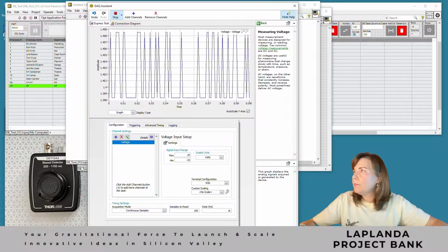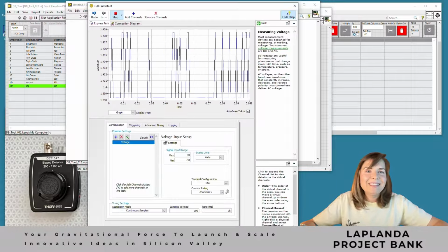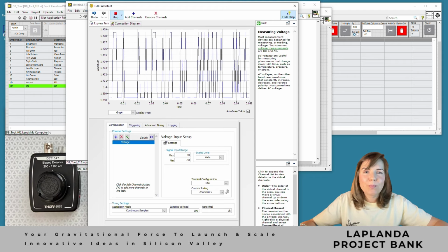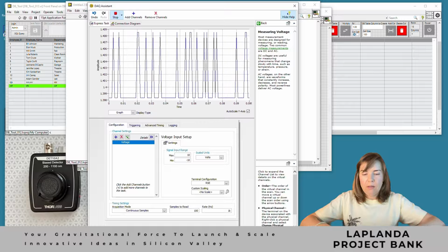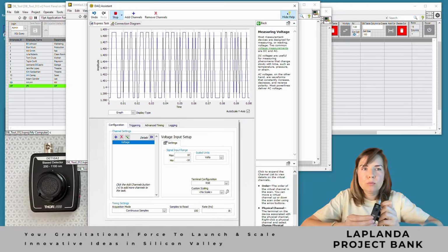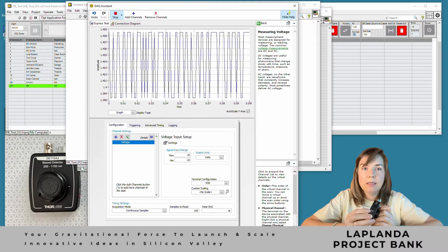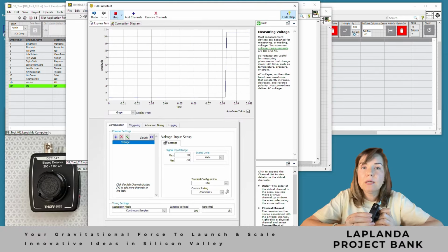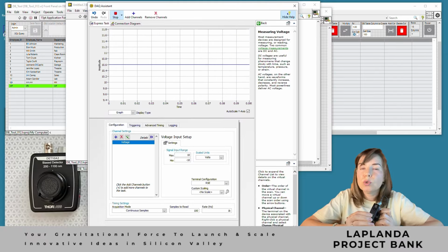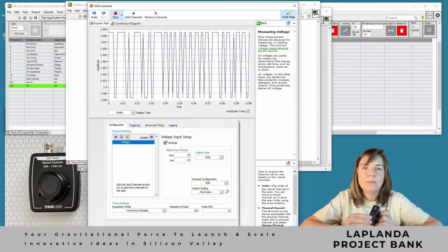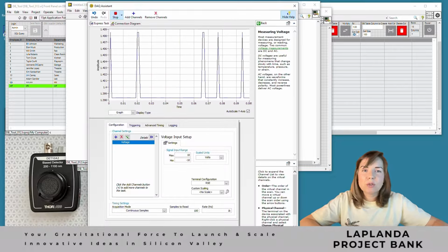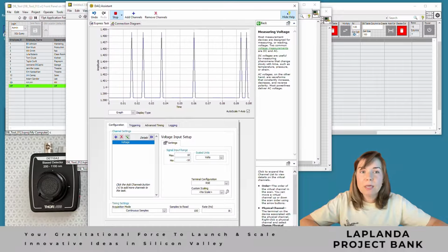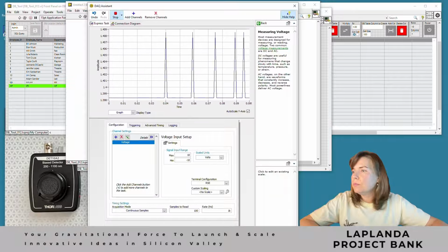I press the run button and we see the familiar white noise. The sensor voltage fluctuating between 1.3 and 1.4 volts. I press the red button. This is the sensor test button, or you can also call it the battery voltage test button. And I see that the battery voltage on the sensor is also 10.6 volts. So we have configured our system. Now let's integrate all of this into the logic.